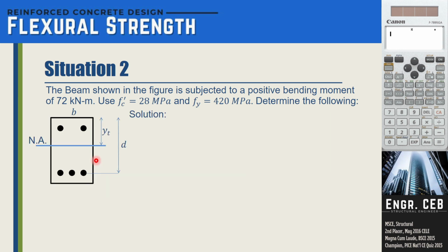So let's start. Again, we should locate the neutral axis. We take the moment of the elements above the neutral axis towards the neutral axis, and we equate that to the moment of the elements below the neutral axis towards the neutral axis. First is the rectangle, so that is b times y times y over 2. Next, the area of the steel reinforcement, which we call A S prime, and then we multiply that by 2n minus 1.